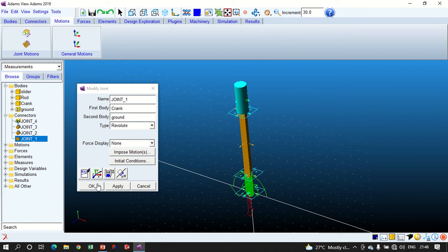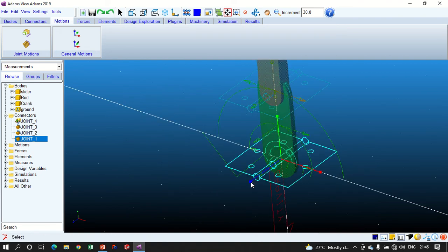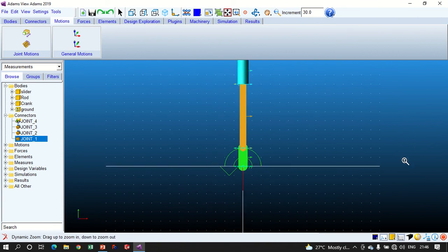Let's say here, first apply, okay, let's say joint, you will see, let me zoom it, here the marker. Blue color is for the Z marker, and the Z marker is the axis of rotation, pointing towards the screen or viewer, and it will use the right hand thumb rule to decide the direction. If Z is oriented in the opposite direction, it would have been clockwise. So remember that. But you can also see it from the arrow direction, no problem.